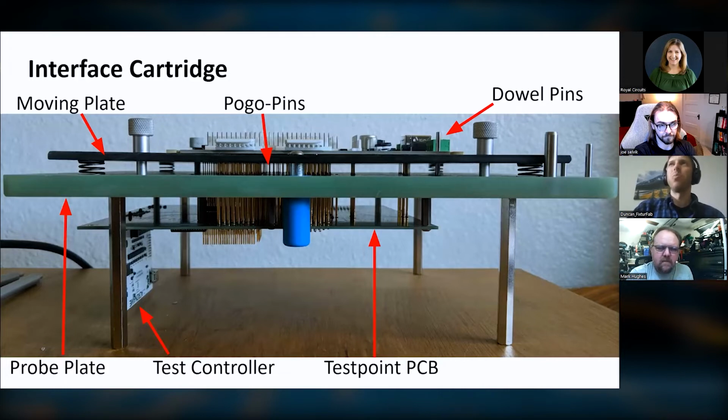Yeah, I believe that's the standard for an M3 clearance screw, 3.2 millimeters. It changes depending on the diameter of the hole though. Okay, all right. There are cases where we'll machine down a dowel pin to fit a custom hole, but typically we try to just use standard off-the-shelf parts.